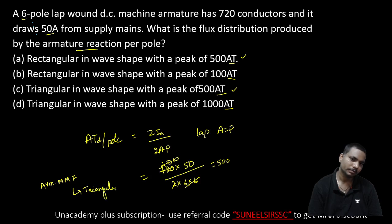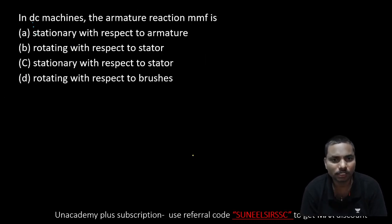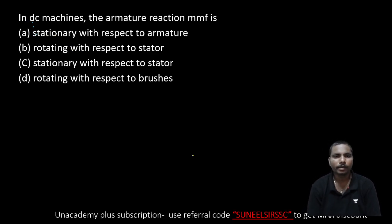Triangular in shape. So triangular in the sense, you can give the answer as options. Okay, triangular in shape. Coming to the next one, the DC machine, the armature reaction MMF. Here armature MMF must be stationary with respect to field MMF. So to get the production of unidirectional torque, both MMFs, that is stator and rotor MMFs, must be stationary with respect to each other.